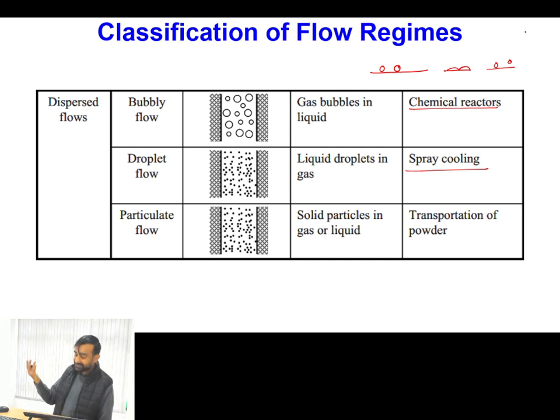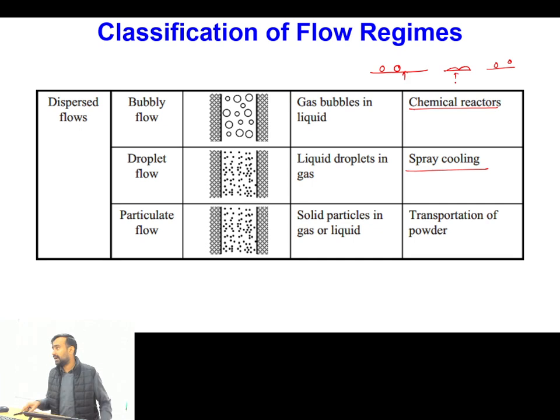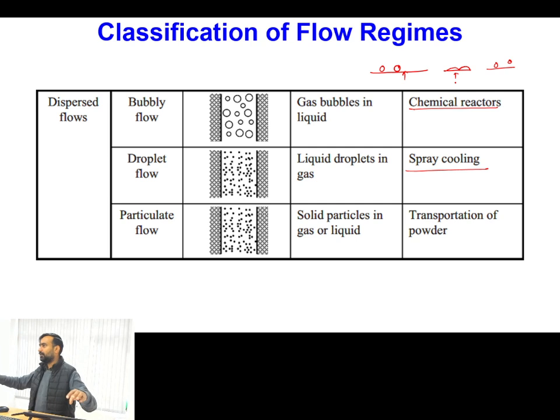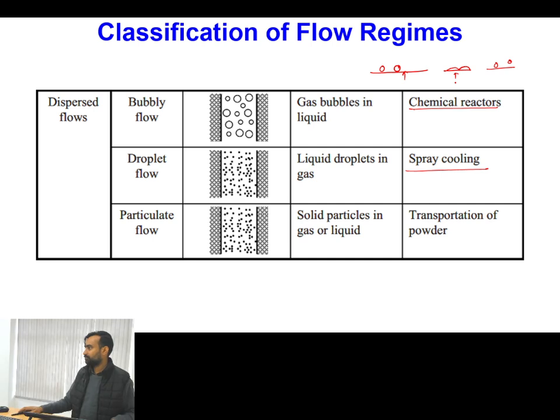But if our interest is to cool the surface, then surface characteristics should be such that a liquid drop which is touching the surface should immediately spread over the surface and form a liquid film. Because if liquid is in contact with the hot surface, then what will be happening? High conductivity of liquid will assist in fast removal of the heat. Hydrophilic. Yes.